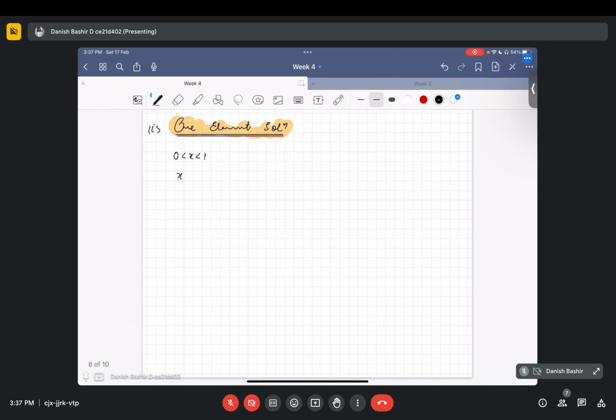So our x1 will be equal to 0, x2 will be equal to 1. And the length of the element L will be x(i+1) minus xi, where i is equal to 1 and i+1 is equal to 2. It will be 1 minus 0, equal to 1. That is the length of element Li. So the nodal parameters in the problem will look like this.